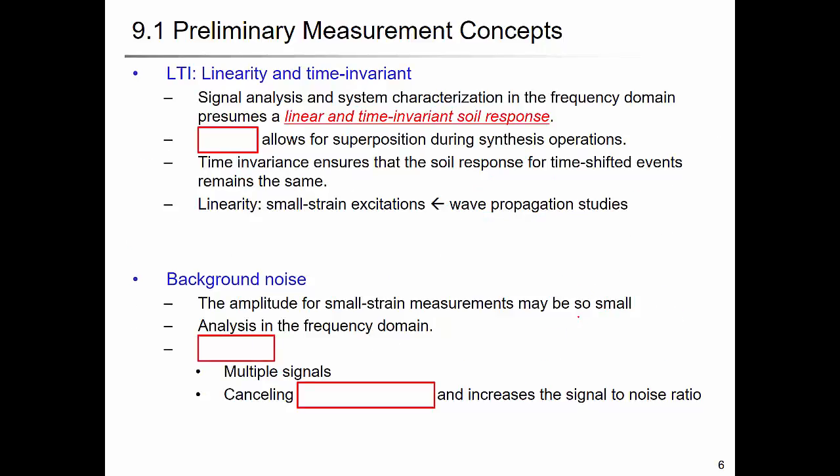In the wave propagation method, we always assume linearity and time invariance. I think we reviewed this concept last week. Signal analysis and system characterization in the frequency domain present the linear and time-invariant response, and linearity allows for superposition during synthesis operations. Do you remember the deconvolution, or the decomposition of the continuous signal? You can decompose the signal into a sum of impulses, right?